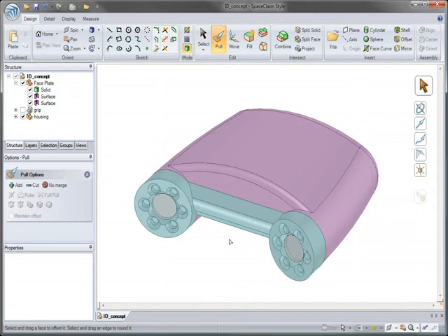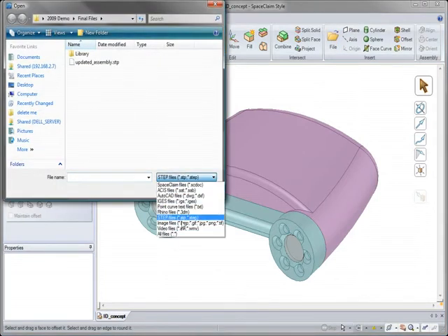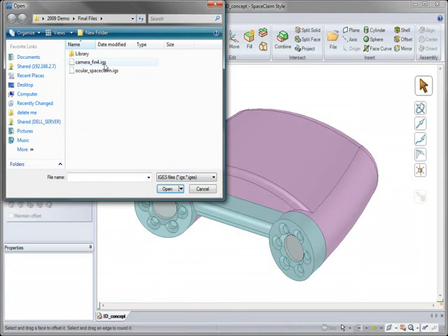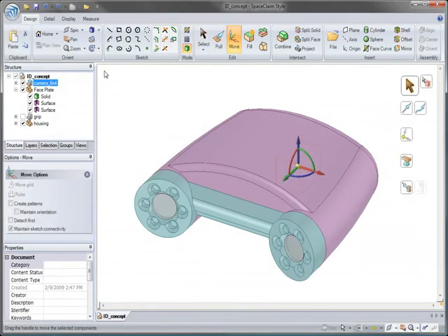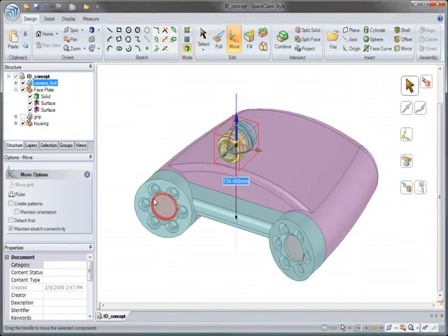Now we'll be making some changes to our design based on engineering recommendations. They've sent us a placeholder for a 4th lens that comes in from the IGES file format, and they'd like us to incorporate it into our design and build the housing around it. They've let us know where it should be placed on the model, so we can move it there and dimension it from the other lens we already have.